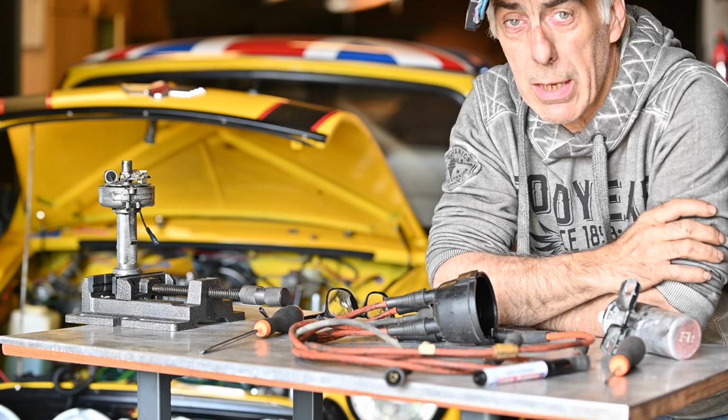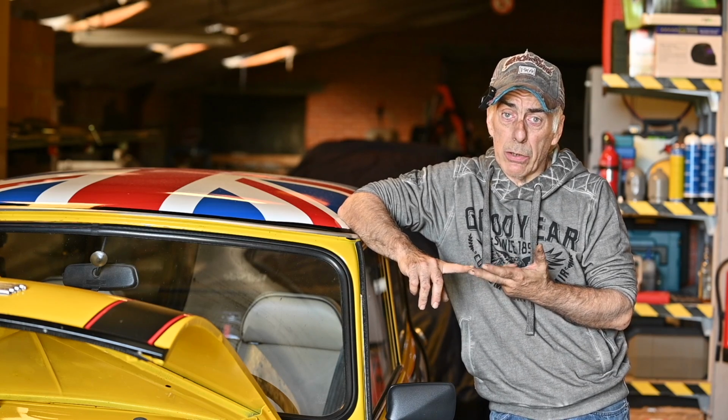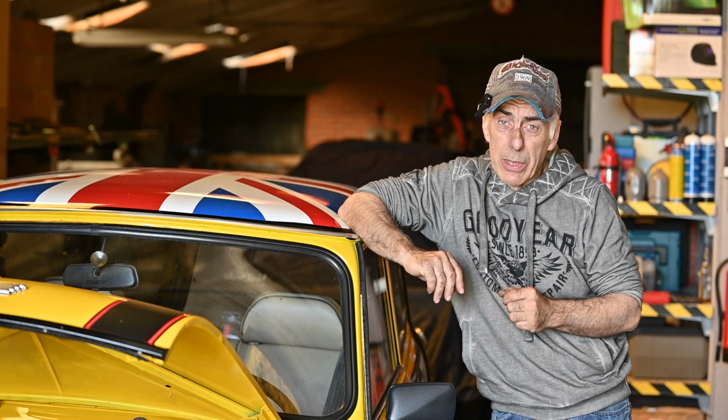Now the question is, how much advance do we need? How many degrees of advance we need depends a bit on how many RPMs we are running. It depends on the engine type. It depends on the fuel you're running, because some fuels have different burning patterns than other fuels. So there are a lot of parameters that will affect the advance that is required.